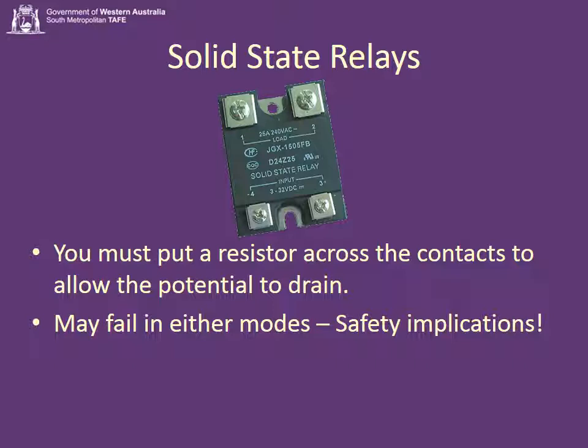Now the problem with a solid state relay, unlike a relay, is that relays almost always fail open. A solid state relay will fail closed as often as it fails open. And that can be a bad thing. You don't want a heater which is permanently on. Because if the heater is permanently on, let's say the airflow stops, then the heater overheats, and then you have a fire.